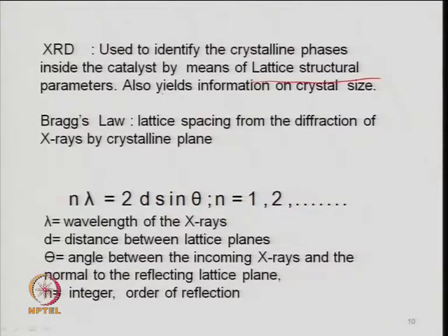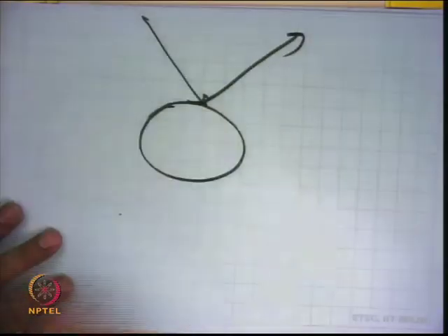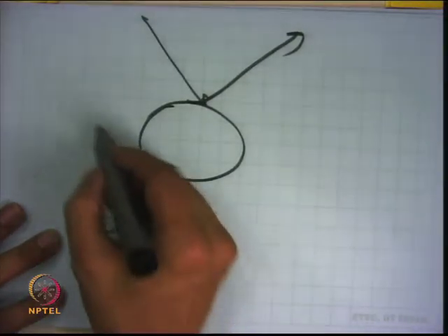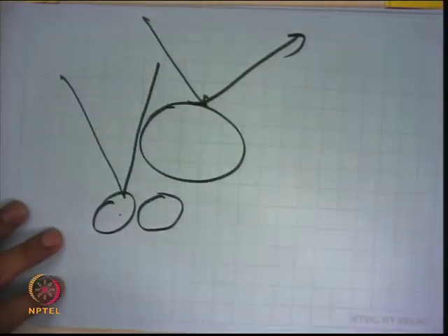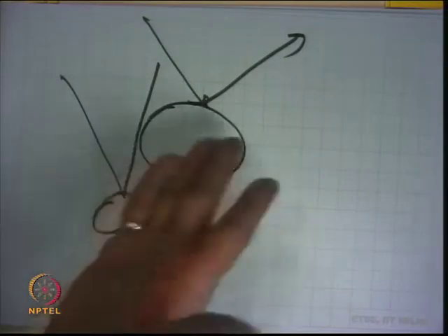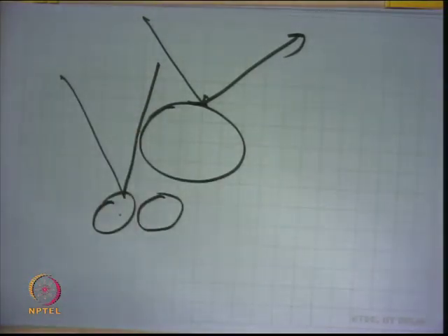When you have the X-ray profiles, we talk either in terms of the intensity of the peak, or the peak width at different diffraction angles. So, it is something like this: an atom is struck by the beam and then diffracts, and similarly in the different layers this will happen. So, here again the beam diffracts. This is the angle of diffraction, because that may change depending upon the surface and the orientation. So, you will have different lattice planes.